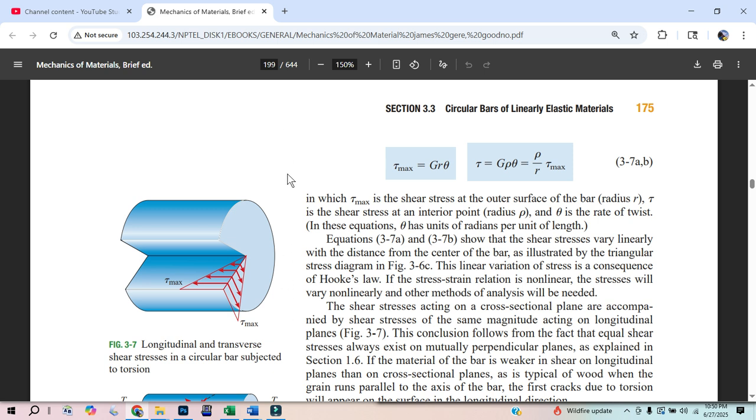Because if I just had those forces in line, you'd be compressing it. But shear is having one force up, one force down, and a distance between them. And if I had that, the thing's just going to spin. So that is the aha moment when you're just like, oh, okay, I get it. If I'm shearing something, I need also equal and opposite forces to counter those. And what we talk about from our analysis is we take a little chunk of material, and it's best to make it a square.